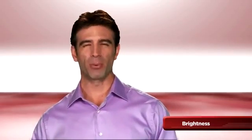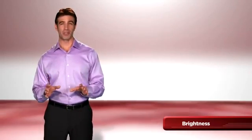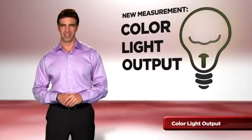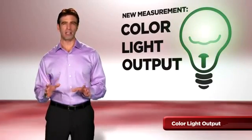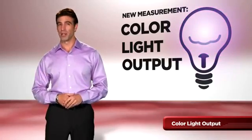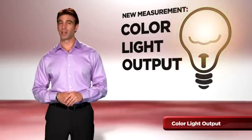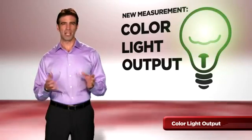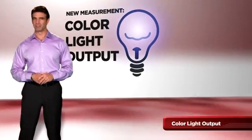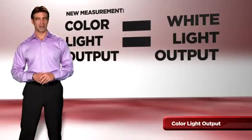However, it is important to mention that lumens, or brightness, is usually only a measurement of white light. It tells you nothing about the brightness of colors. Fortunately, several major projector manufacturers have recently introduced a new metric called color light output. Color light output provides valuable information about a projector's ability to deliver bright colors, which is critical for projecting photographs, videos, and other colorful graphics. If you're projecting images with color, look for a projector with high color light output. Ideally, the brightness of color should equal the brightness of white.